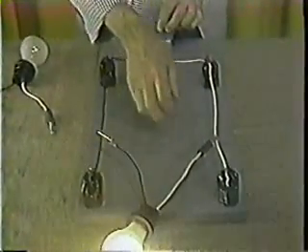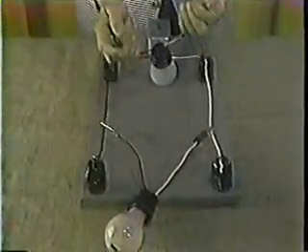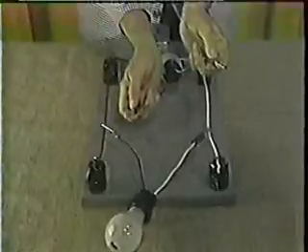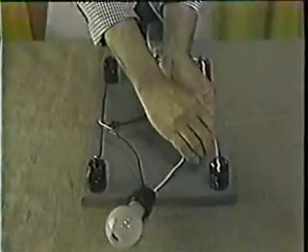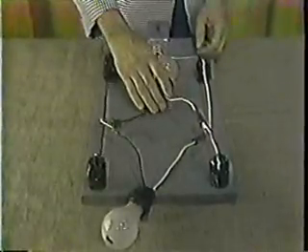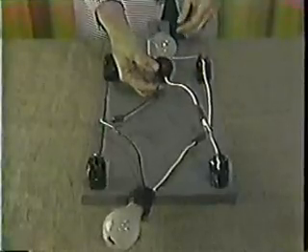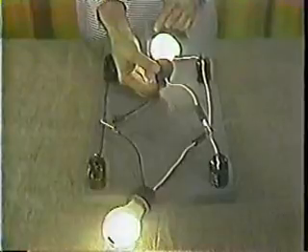When we connect a load, such as this light bulb, across the system, it lights up. The resistance to flow in the filament causes it to heat up, and it gets hot enough to give off light as well as heat. Since this is a 60-watt bulb, it will use 1/2 amp of current at 120 volts. If we put another 60-watt light bulb here, it will also light up just as bright as the first one.